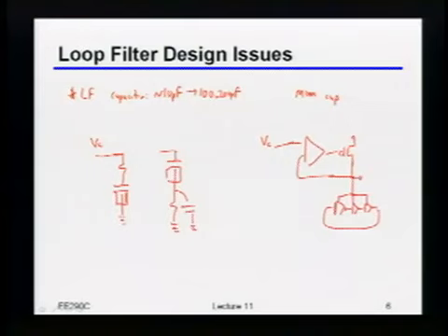So what would that do in this context? What would happen to us if we actually tried to use a MOS cap with that MOS cap having gate leakage in it? What would that do to the PLL? Frequency would drift. Yeah, basically, if you looked at the control voltage, what you'd end up with is that, let's say you nominally wanted to start somewhere, but you've got that leakage on there, right? So it just starts drooping down, okay?